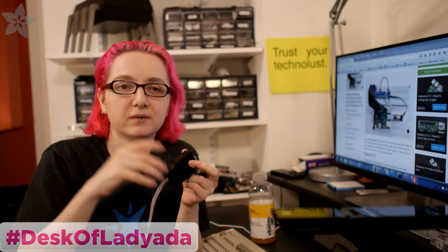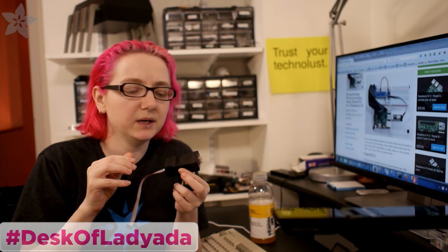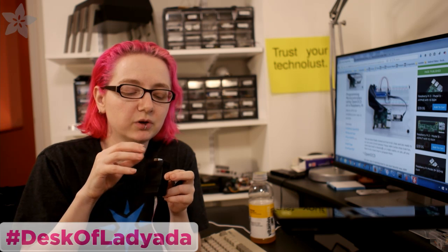Now, I come from Atmel land, and I actually designed the USB Tiny ISP for programming 5 volt and 3 volt logic. It's based on Dick Streefland's code called Tiny ISP. The protocol to program AVRs is actually just SPI. It's a really simple 4-wire protocol: clock, data in, data out, and reset, and you send 8 bits and it gives you back 8 bits. In the data sheet, it even gives you the 8 bits you send to read the fuse, and the 4 times 8 bits to write a fuse, and then you read flash, write flash, EEPROM.